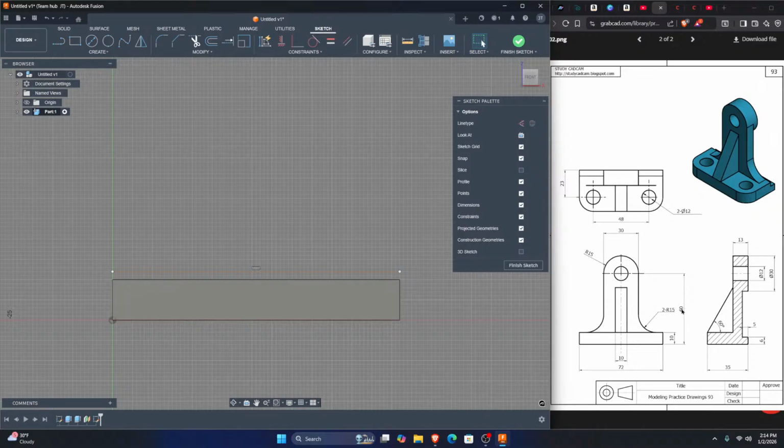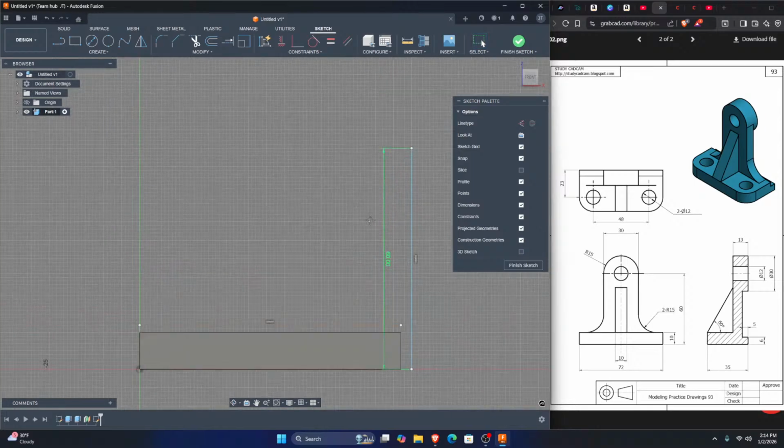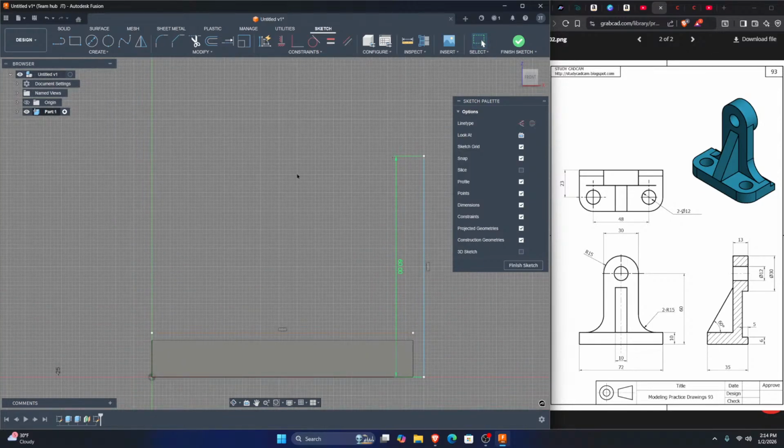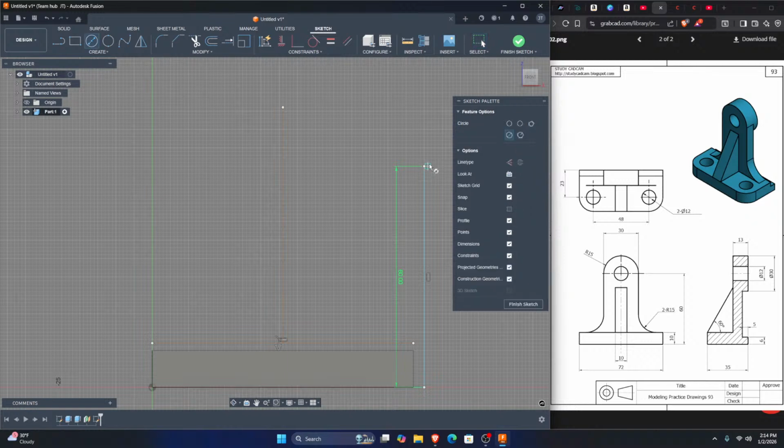It looks like 60 millimeters. I will create another little reference line here just to make it easier. I'm going to put 60 millimeters, and that should be our height for the middle of our circle. So now I can reference, see where this triangle is. That's our middle portion. I'm going to create another construction line so I have neat and tidy things. We can always get rid of these later. So here is our reference point, and we will do a diameter of 12 millimeters.